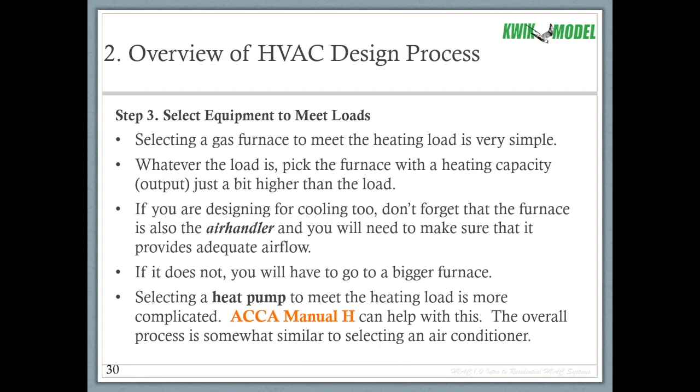The vast majority of designs that I've done have been gas furnaces, but you're starting to see a trend towards electrification, more heat pump heating systems. But if you do have to pick a gas furnace, it's quite easy. You'll have a heating load number, and then basically you just pick a furnace with an output capacity that's just slightly higher than that load.